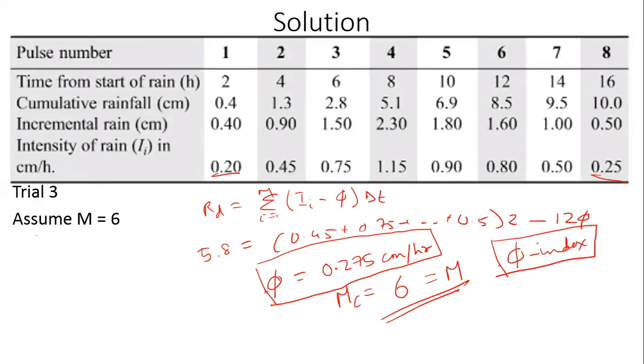Okay, in the first 1 hour I may get a rainfall intensity of so and so. The next 1 hour my rainfall intensity will be so and so. And during the course of the day I'm going to receive this much rainfall. What do you do? You simply create a hyetograph, and using the phi index that you have obtained from past information, your watershed is not going to change its behavior, right?